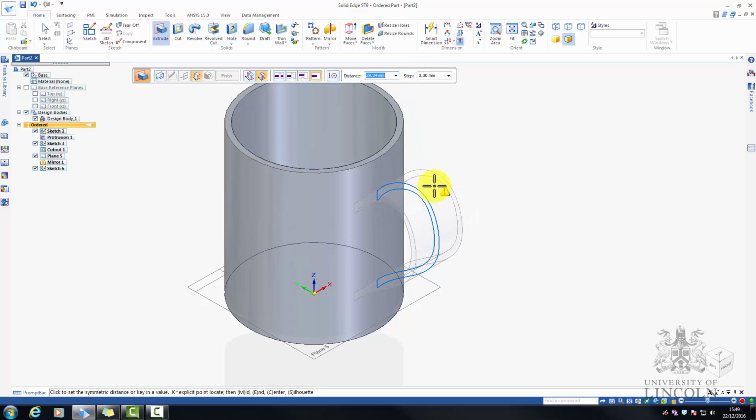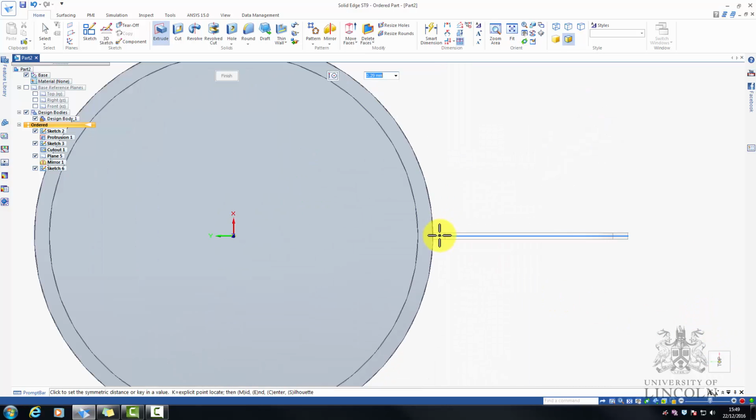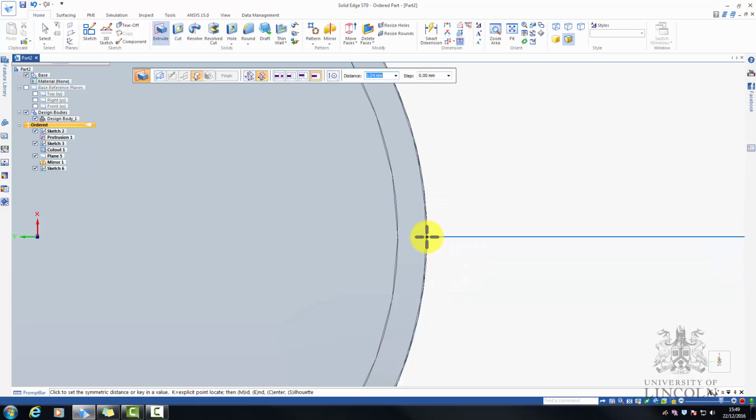But we have an issue developing. Now I suspect it's because if we look from directly above, we have a region where the handle is just about in contact with the mug, but as it moves away, obviously it becomes an infinitely thin wedge. So I think it's going to come up saying I've got an issue.